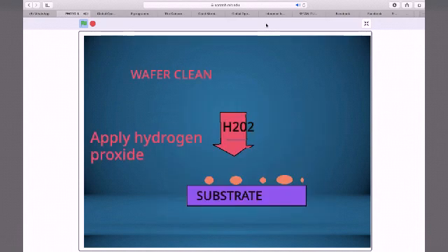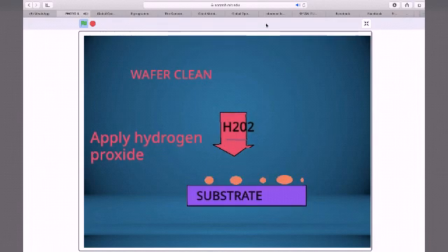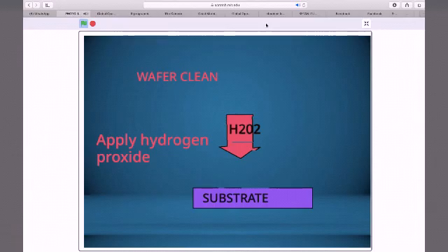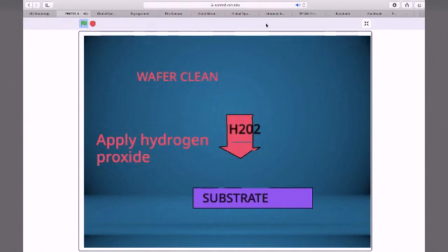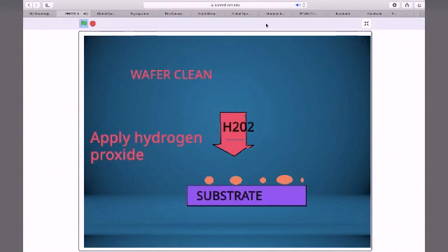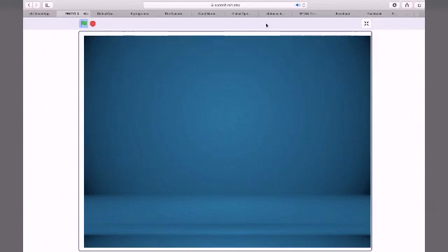The silicon wafer is treated chemically with hydrogen peroxide to remove any contamination that may be present on the wafer. Contamination may come from the removal of the wafer from the pods and from the robot arm which the wafer sits on. Then a layer of silicon dioxide is placed on the wafer to act as the masking film. HMDS (hexamethyldisilazane) is placed on the wafer to increase adhesion of the photoresist to the wafer. This reduces the amount of resist needed in the coating process and is referred to as RRC, reduced resist consumption.